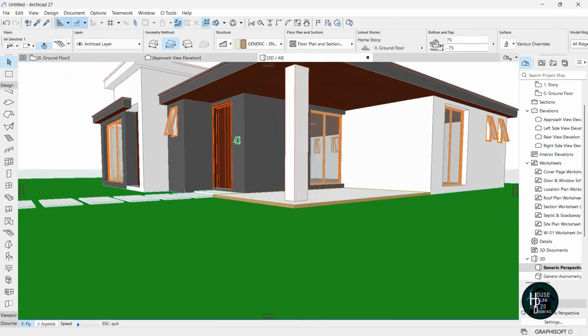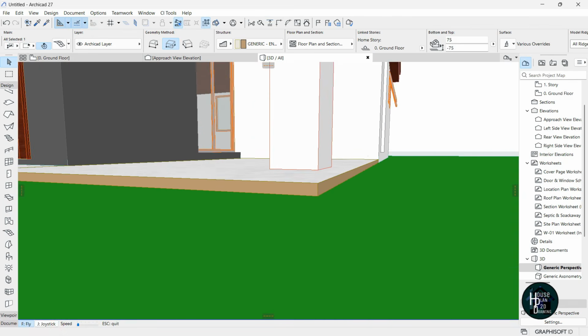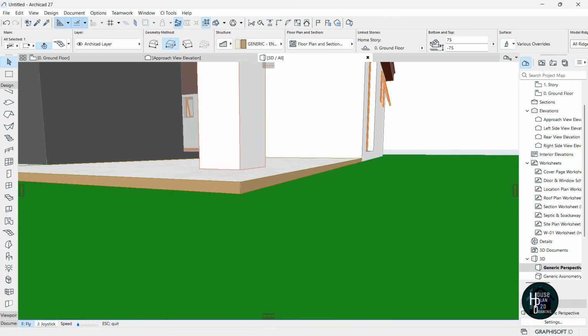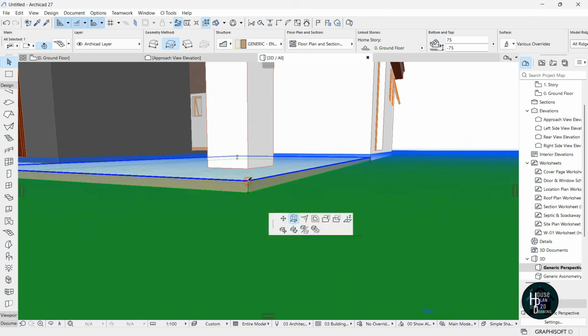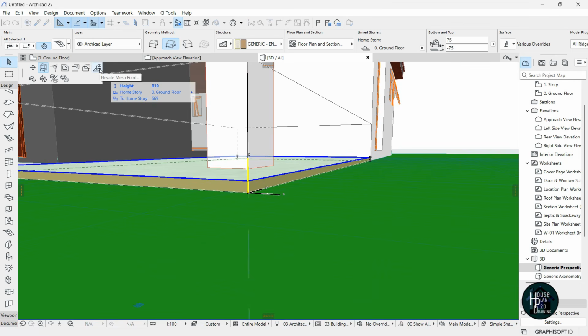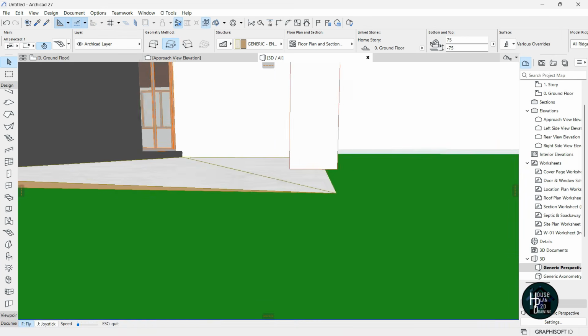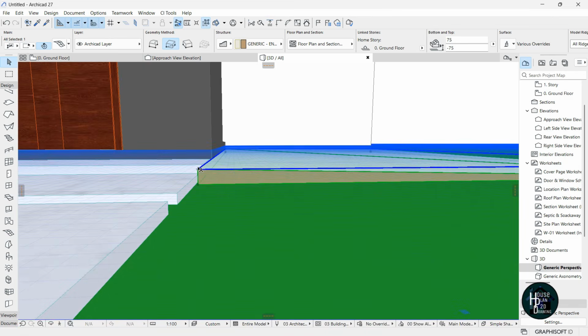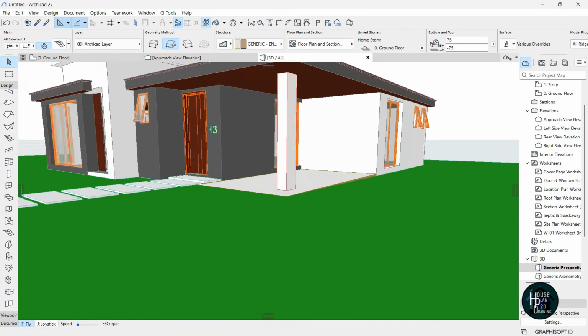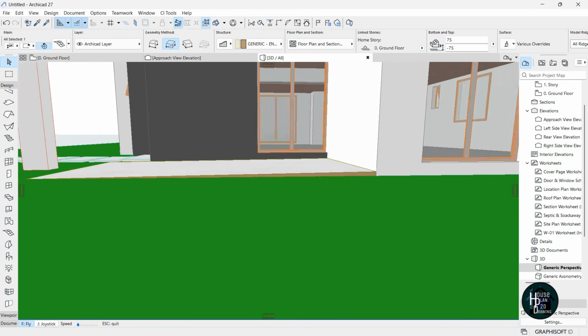And for this side here, just click this, come and select this elevate mesh, click on it and move it down. Come to this other side too, click this and move it down too. Alright, so you're going to be having it being something like this.